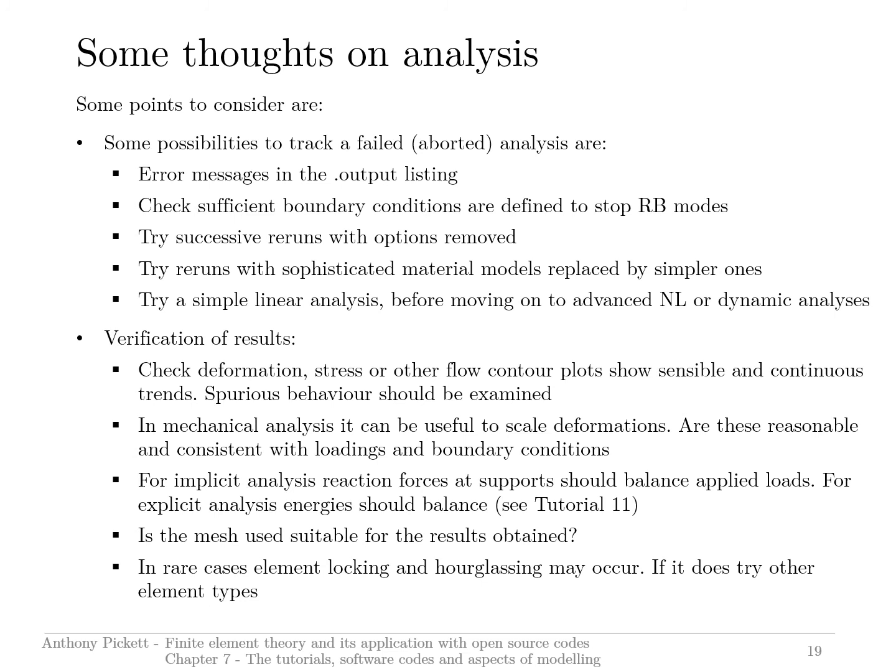Some things you should check when you've got results. Have a look at the deformations. I do this in the tutorial following these lectures. I use a scaling factor on the deformations and have a look at how the structure deforms. This can be very useful to get an idea whether or not the deformations are sensible compared to what you expect regarding the boundary conditions and the applied loading.